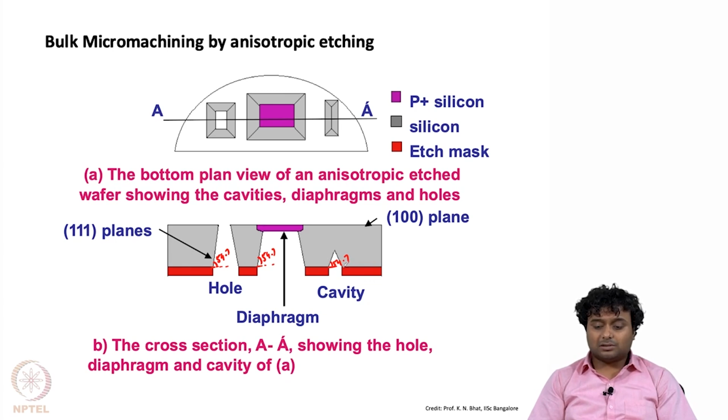Whereas this is the smallest opening hole, so here both the sides meet much before it can reach the bottom side of the plate. So this through hole, this membrane and this V-shape hole all are made using the same KOH etching, by just using an etch stop layer here and different kinds of hole openings.